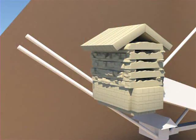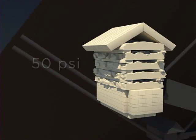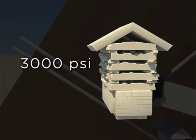Now, to get a sense for its effectiveness as a structural element, I did a flexural analysis, very similar to the one we did for the Temple of Artemis architrave beams just a few lessons ago. My calculations show that the maximum tensile stress in this slab is actually quite low. It's about 50 pounds per square inch, compared with the ultimate tensile strength of about 3,000 pounds per square inch for granite. The strength is 60 times larger than the actual stress. Clearly, the king's chamber was built to last.